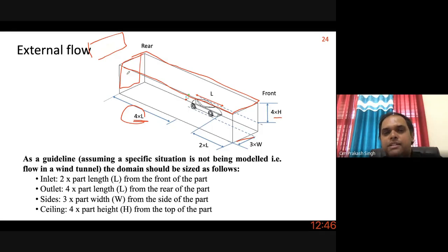Now again, one more reason concerns the rear wall. Let's say there is a reverse flow like this near this region. Ideally at the outlet you may put a pressure outlet boundary condition, or something related to pressure. Since the flow is recirculating here, physically it will tend to drag the outside fluid inside also. So in CFD, you will sometimes see a warning that reverse flow is happening.